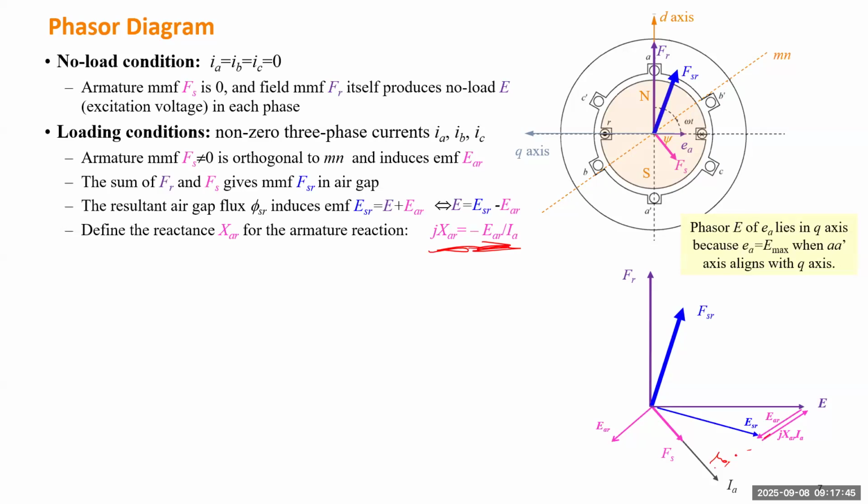So this is the ideal generator without any resistance, without any leakage of flux. What I mean is, there will be some flux, right, in the magnetic field inside of the generator, but there's no leakage of flux. There's nothing like flux going outside. Everything can be fully utilized to help connect the rotor and stator. If that's the case, it's done. So this will be the final phasor diagram.